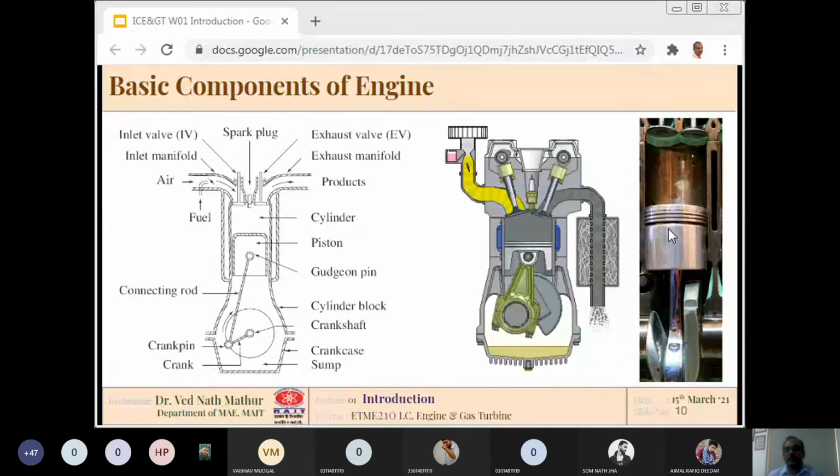The purpose of the piston ring is that it does not allow the entire piston surface to rub against the cylinder surface. Only the rings are in contact with the cylinder, and also there is an oil film. So surface to surface contact is avoided. After some time, when the ring gets worn away, you can replace the ring.